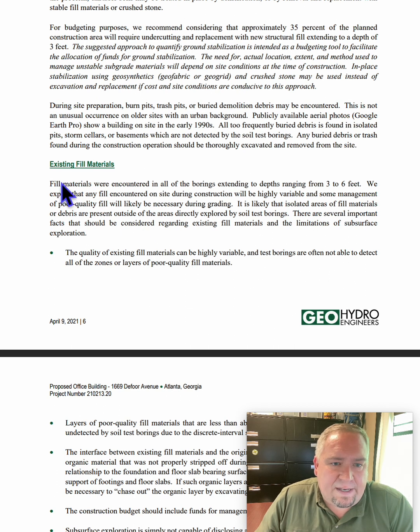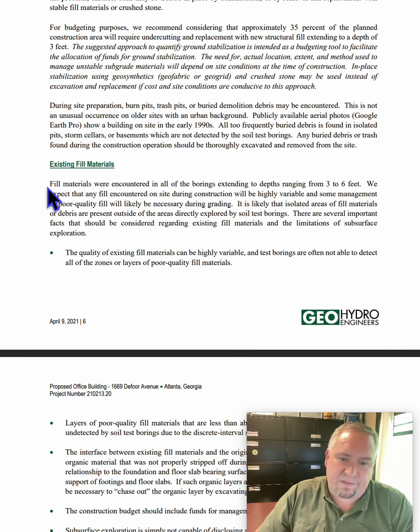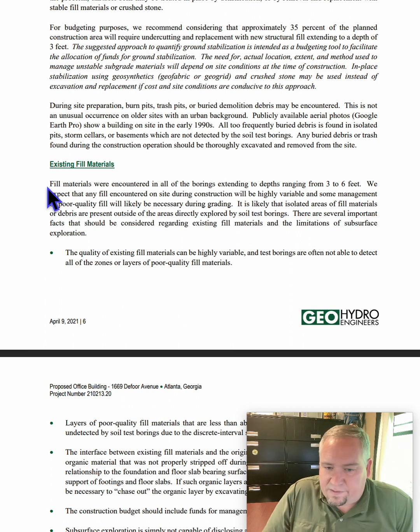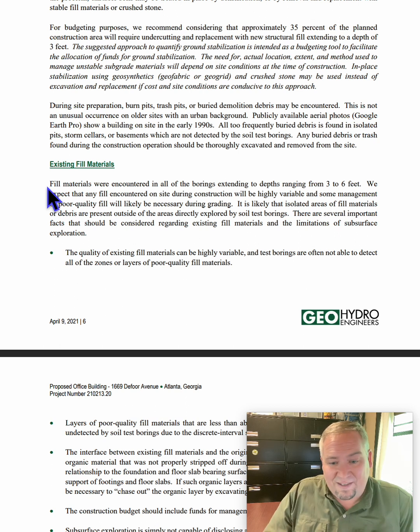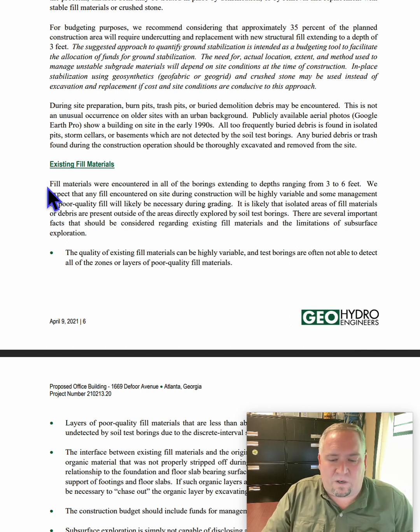Let's see. Existing fill materials. So whenever we hear fill materials, likely somebody just dumped some dirt and slicked it off. So it wasn't checked on the bottom, properly tested along the way, or the dirt wasn't tested. So usually these soils are not up to the standards that a commercial property would need, or even residential properties for that matter. And the higher the profile of the project, the more clarification and verification we need on our dirt.